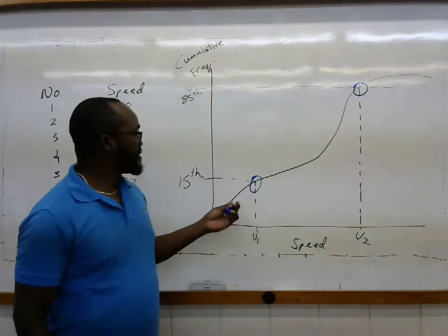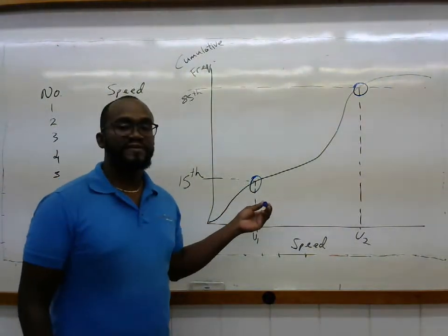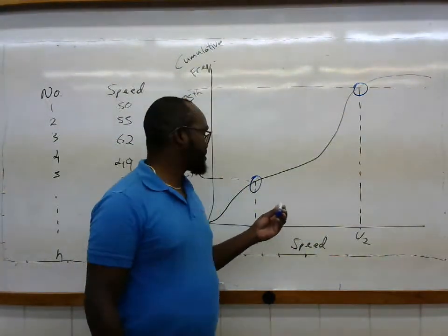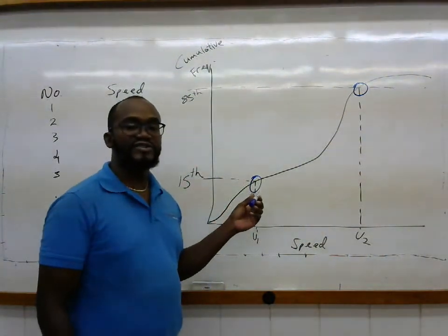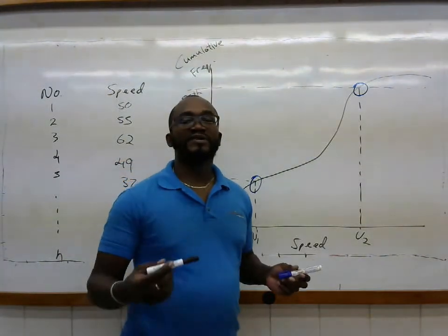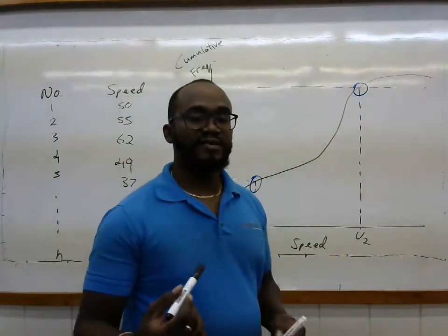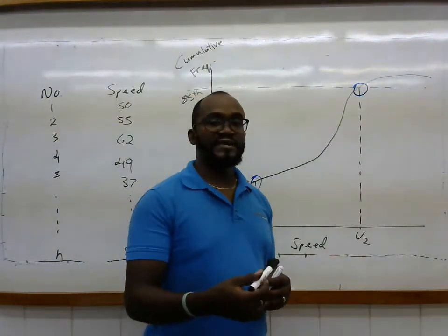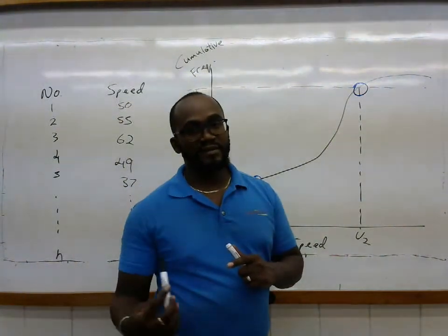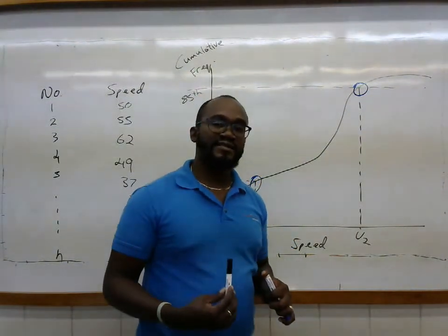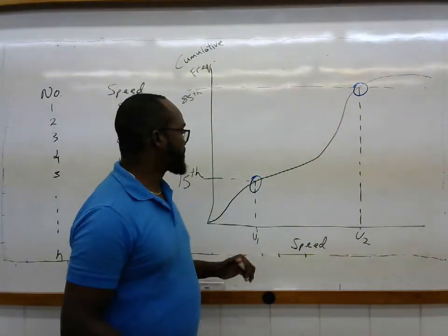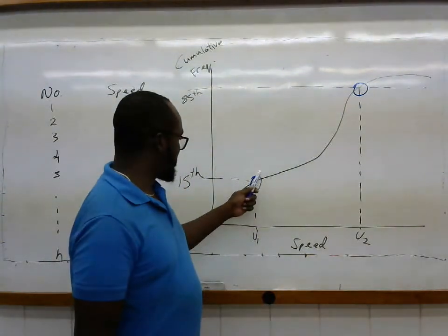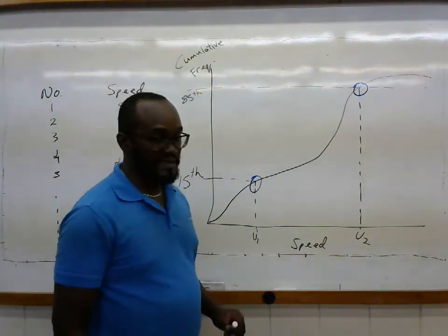So what we do is that we tend to set the timings for pedestrian crosswalks at the lower end of the curve, so we ensure as best as possible the majority of users can traverse an intersection without motorized traffic catching the green light and causing injury or death to the pedestrians. So that is the purpose behind the 15th percentile speed.